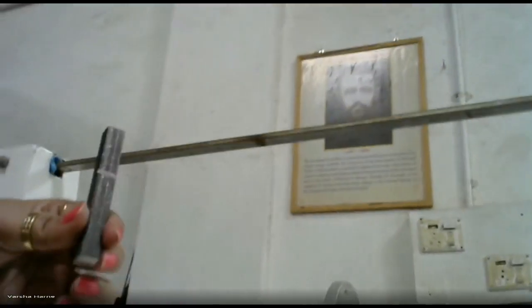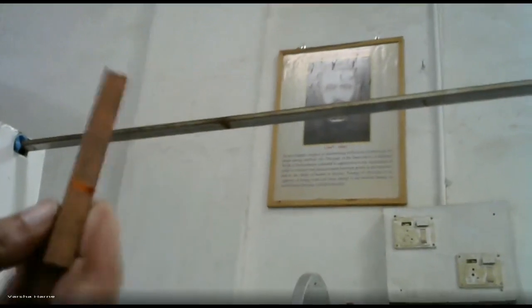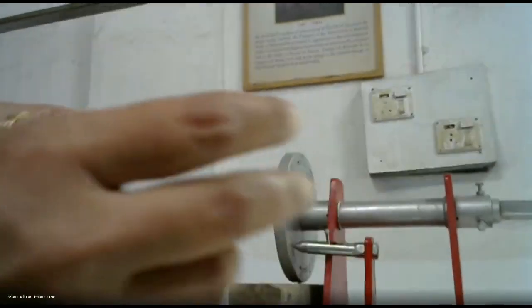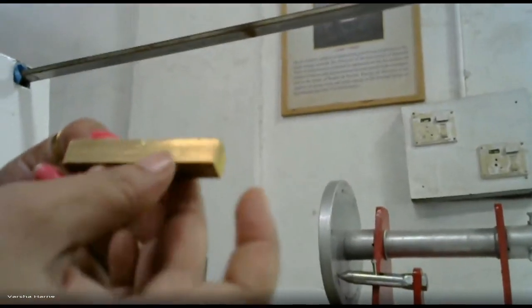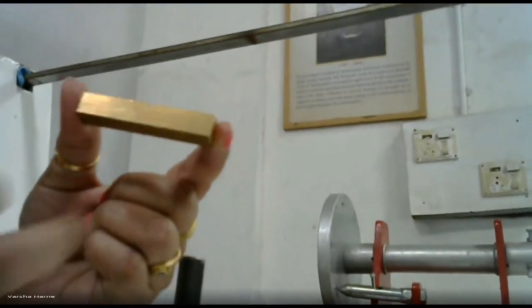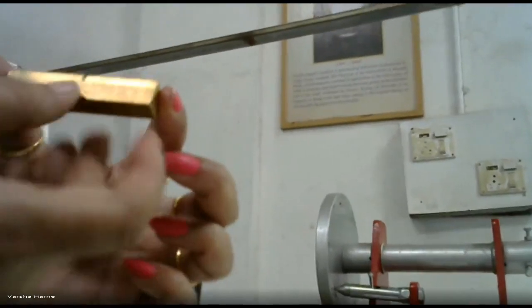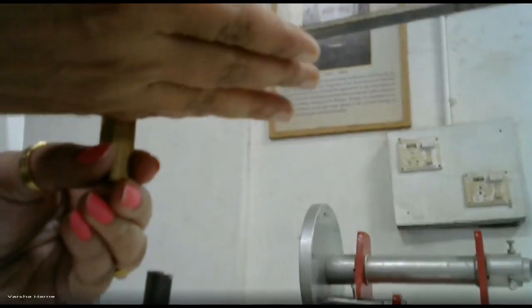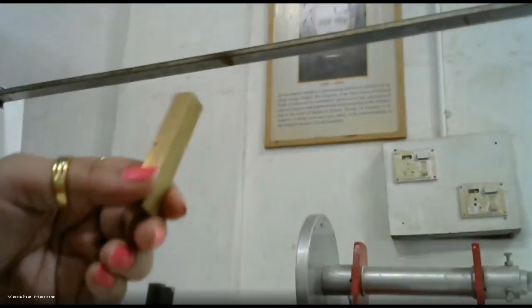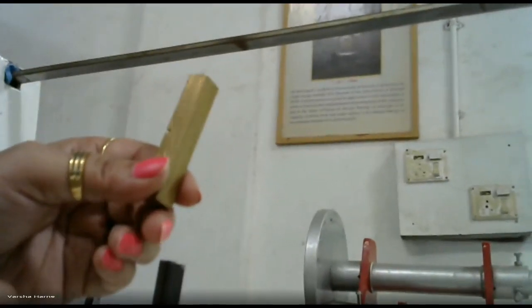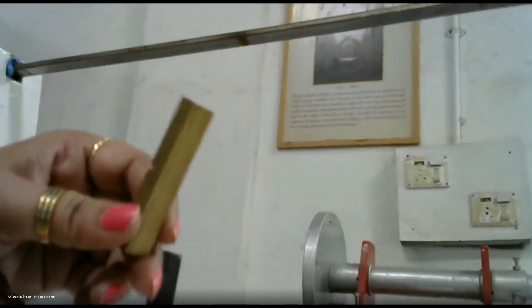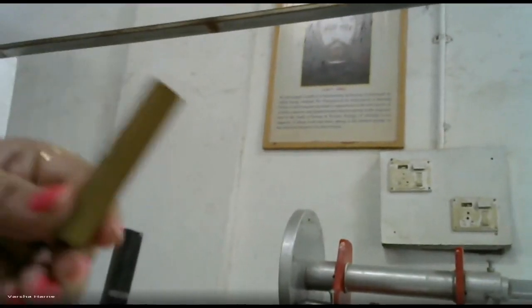Now see here, this is our mild steel, this is copper, and this is brass. So first of all, you have to measure the dimensions. Similarly, for Charpy impact, we place our specimen as a simply supported beam, and the hammer is applied at the backside of our specimen, suddenly. So we have to check the impact strength of brass, copper, and mild steel material, which one is preferable for our constructions. So we have to check the behavior of the material.